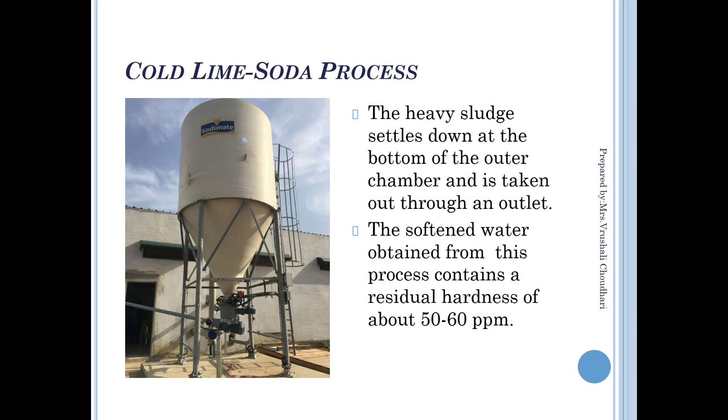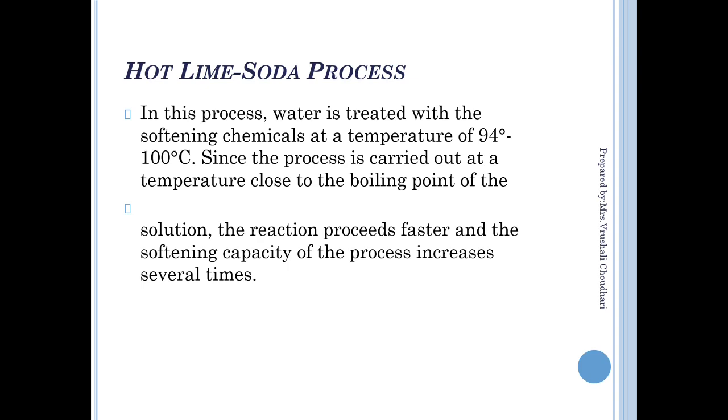This is the actual soda lime plant where the reaction or removal of hardness of water will take place. In this process, we can make soft water down to 50 to 60 ppm. Next process is the hot soda lime process.